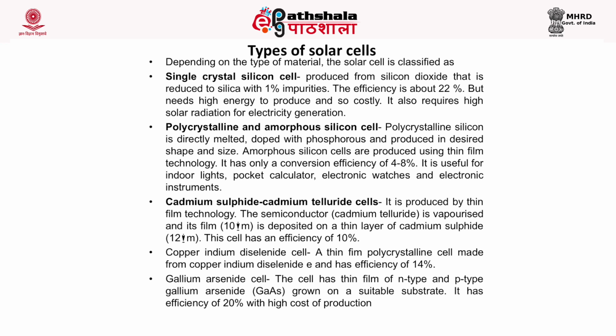Cadmium sulfide, cadmium telluride cells. It is also produced by thin film technology. The semiconductor, that is cadmium telluride, is vaporized and its film of 10 micrometer thickness is deposited on a thin layer of cadmium sulfide of 12 micrometer. This cell has an efficiency of 10%.